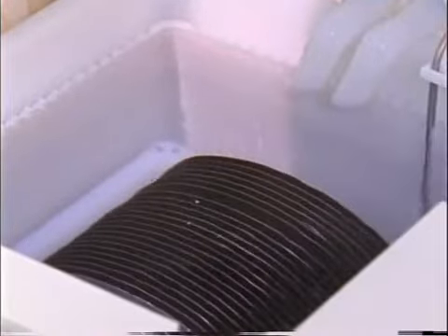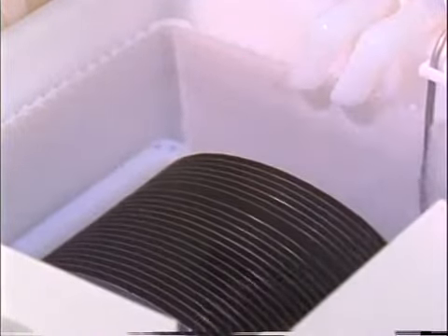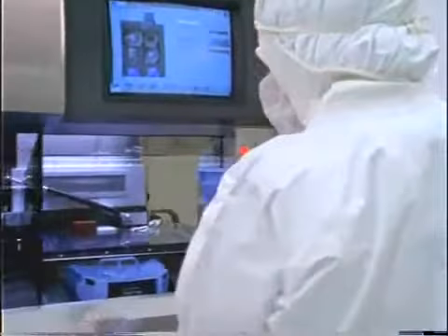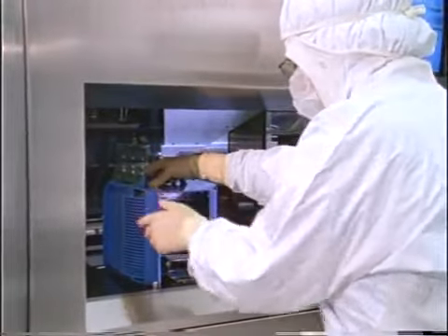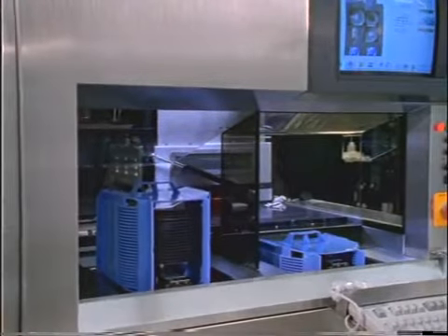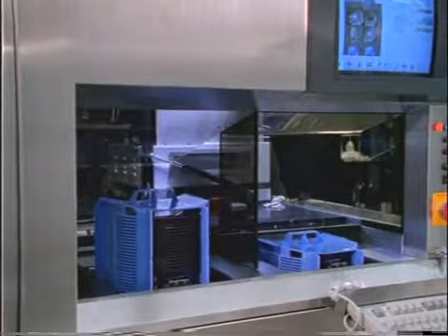Although acids can be used for etching, most wet chemicals etch in all directions at equal rates, which can result in undercutting of the photoresist. Undercutting could create an inexact transfer of the mask. When a critical fine etch is needed, the wafers undergo a dry etching process called plasma etching.